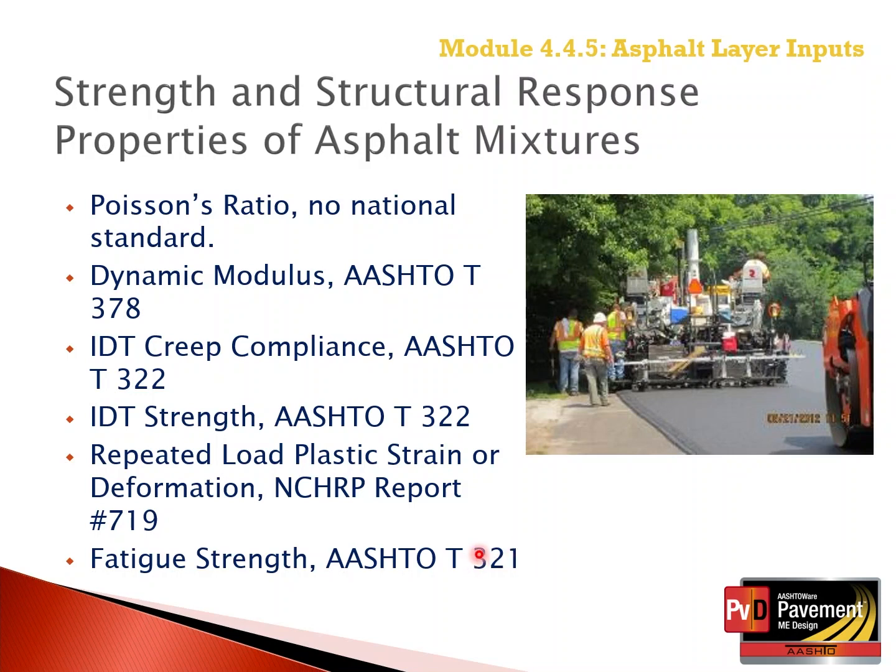As noted for the other asphalt layer properties, the asphalt layer strength and structural response properties should be measured on specimens representative of the condition after construction and not at the design laboratory volumetric properties.